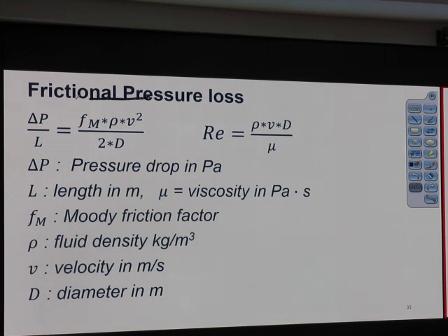Oh, Arif, can this equation be used for vertical flow, like flow in a well, to estimate frictional pressure loss? Or is it only for pipeline? It doesn't have the term gravity in it, so I'm guessing it can be used. For the term with the gravity, we will have that delta H thing. The friction part stays the same. So the friction part for flow in the well is still this equation.